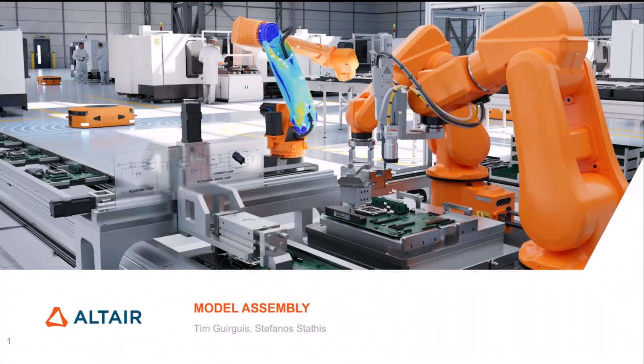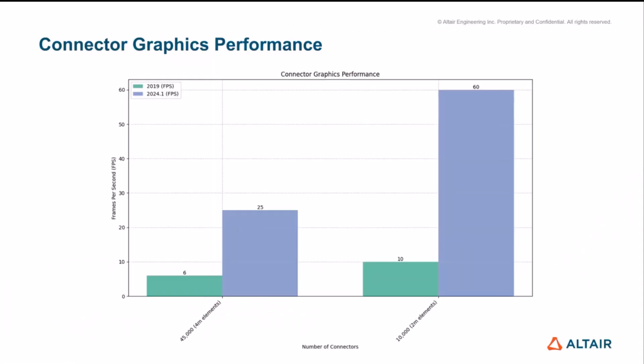Features that have been introduced for the model assembly or the connector workflows. The first thing that we're going to go through today is graphics performance. One of the biggest things that we've had over the last few years is that with large numbers of connectors, people were seeing slowdown in pan, rotate, zoom, those sorts of things. So for 24.1, we have dramatically overhauled how the connector graphic implementation works.